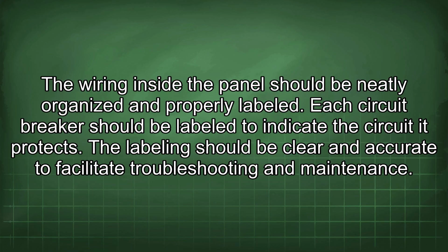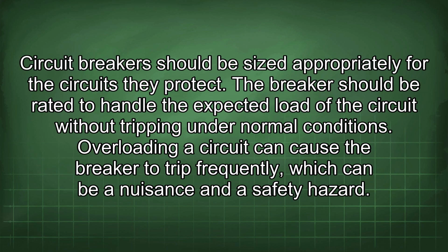Each circuit breaker should be labeled to indicate the circuit it protects. The labeling should be clear and accurate to facilitate troubleshooting and maintenance. Circuit breakers should be sized appropriately for the circuits they protect. The breaker should be rated to handle the expected load of the circuit without tripping under normal conditions.